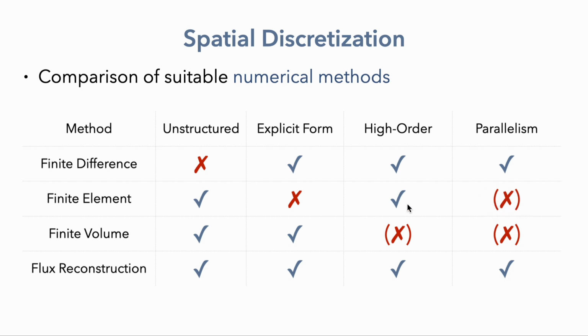If we compare FR to the finite volume method, there are high order extensions like WENO5, for example, but these are particularly challenging to implement around things like general boundaries. And another disadvantage of the finite volume method is parallelism. With finite volume, when you increase the order of accuracy, you inherently increase the amount of parallel communication.